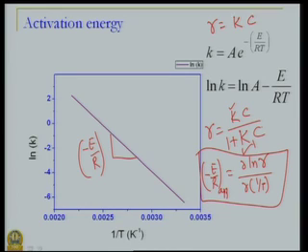Now, the dependency of diffusion rate processes on temperature is much milder than the dependency of kinetic rate constants on temperature. Kinetic rate constant on temperature is exponential, as we saw here. So, what happens when you take a derivative like this? You get an activation energy value which is fairly low. In fact, if the diffusion process is independent of temperature, then the activation energy or the apparent activation energy for such a process would be 0.